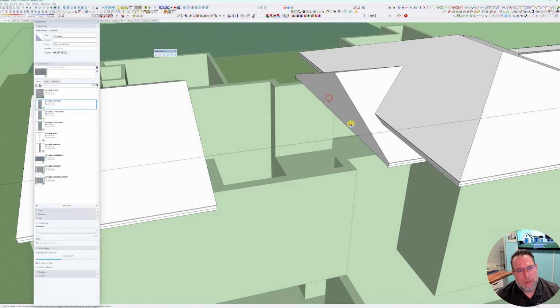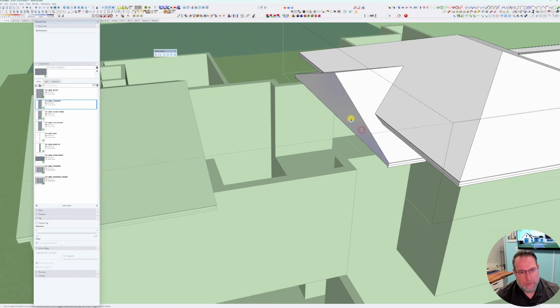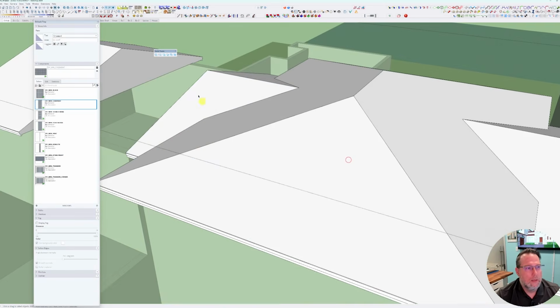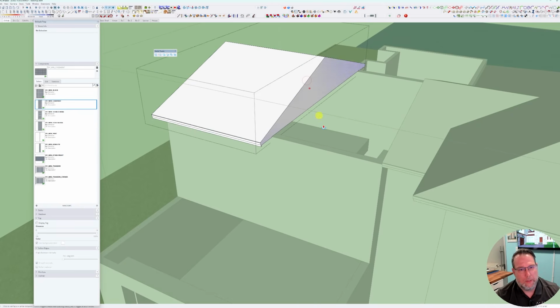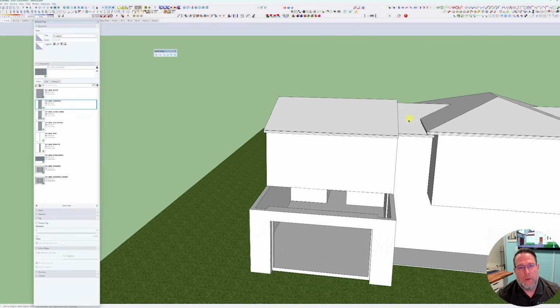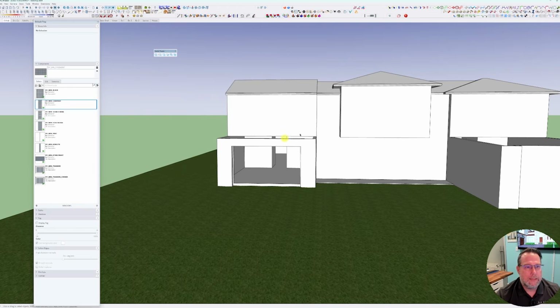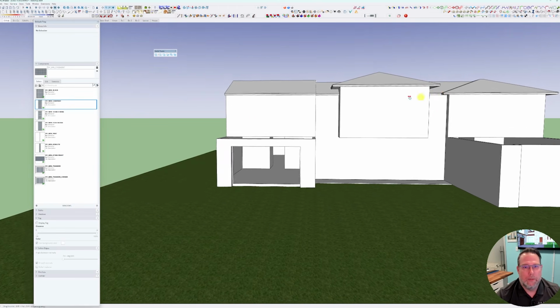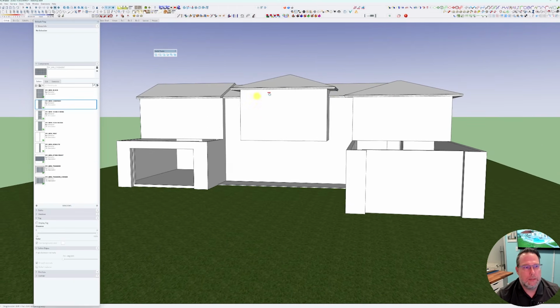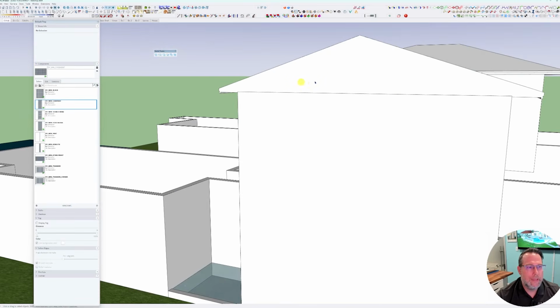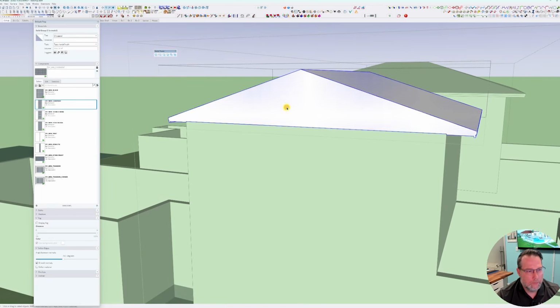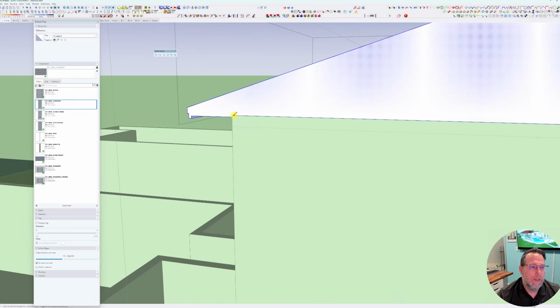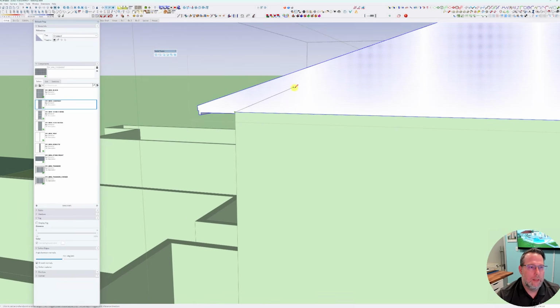So now we can just come in and push-pull this guy to here, and we will then push-pull this guy to here, and we can quickly say, okay, well, that's how a gable on this side would look, and this is how a hip would look on this side. And then once you really start getting into, okay, we really like the gable, how do we, we then can use solid tools and inferencing and all those good sorts of things to actually build a real gable.